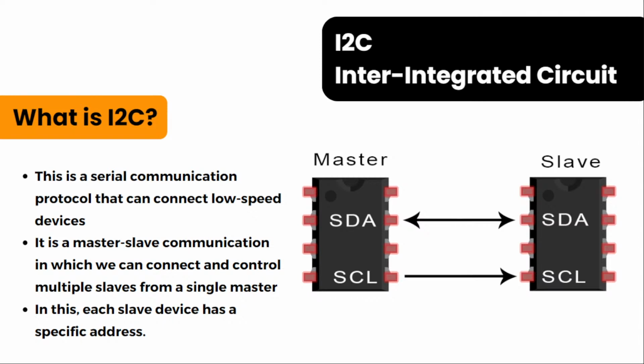Like UART communication, I2C also uses only two wires to transmit data between devices. One is serial data and another one is serial clock line. The data line is for the master and slave to send and receive data, and the other line carries the clock signal. I2C is a serial communication protocol, so data is transferred bit by bit along a serial data line.